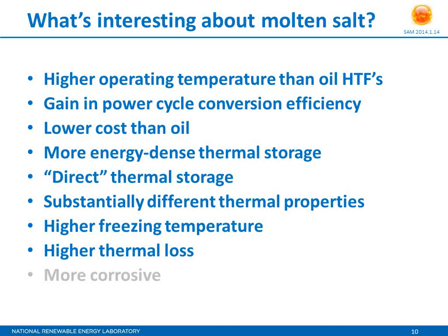The salt has a higher solidification temperature than oil does. So that means now instead of letting our oil cool down to near ambient at night and not having substantial problems, or maybe say 100 degrees C, we have to keep that salt above 250 or 260 degrees C in order to prevent it from freezing.